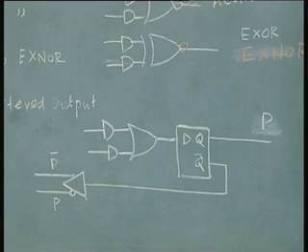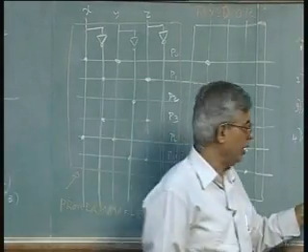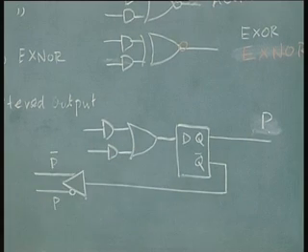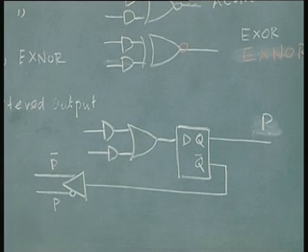Combinational logic will be taken care of by the array of the AND and OR, sequential part will be taken care of by the registers which are available at the outputs of this combinational logic. So, in a single chip or device, I can produce a whole system instead of having to separately connect the combinational logic to flip flops.